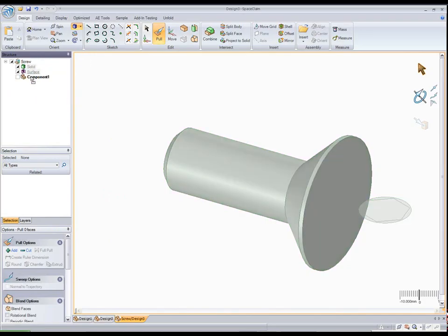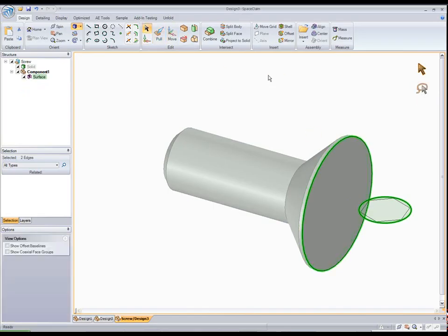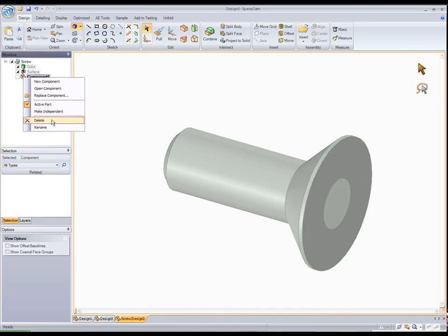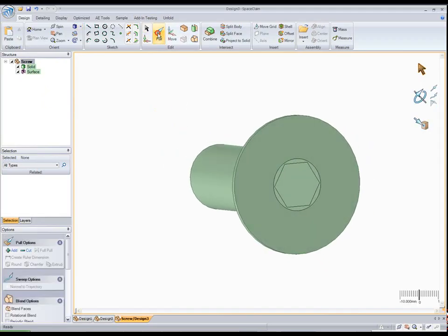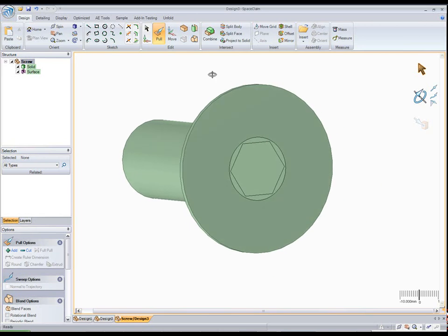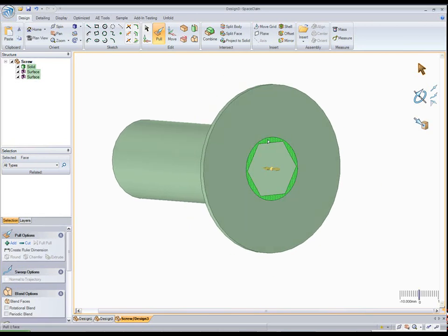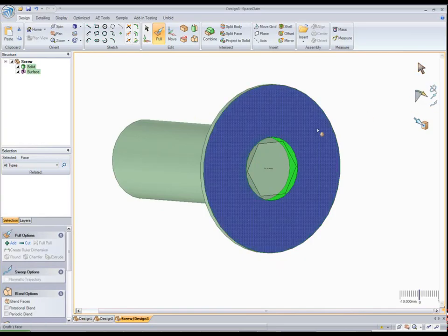And I'm actually going to use assembly tools to assemble the images, if you will, of the different views together. These just become surfaces in SpaceClaim, so I can just make these concentric and align to each other. And now I've got the right information. Now this drawing actually didn't include any information about the depth of this hole, and really I would probably download this from a website of my supplier or use our TraceParts library to model something like this normally. But here, since I already had the information, it's pretty fast to make a 3D bolt.